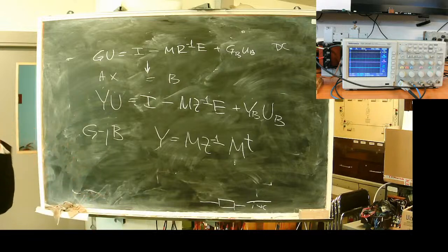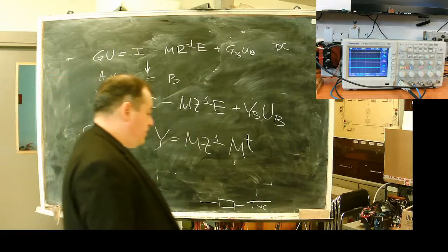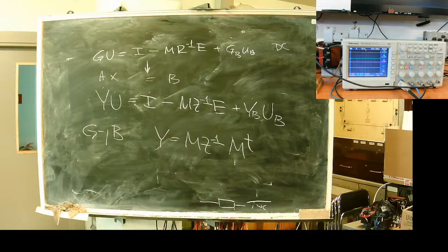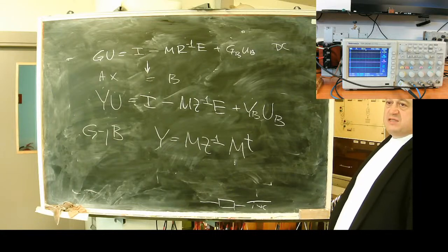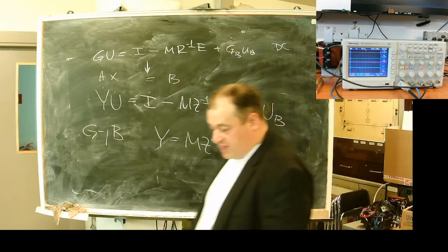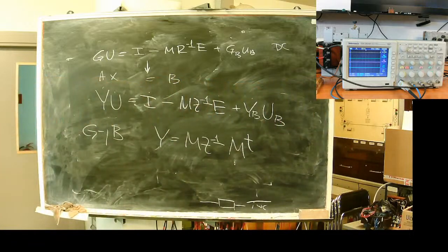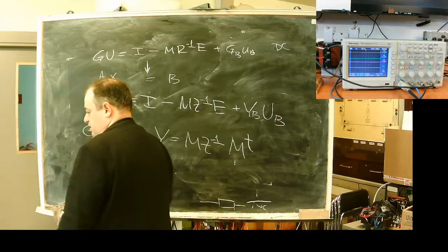You have to apply Kirchhoff and Ohm law by assuming that real values, what we observe, are projections of some vectors on a complex plane, and by introduction of complex resistance with an imaginary part, to reflect a phase shift introduced by the ability of capacitance and inductance to store energy. It's where the key element lies.